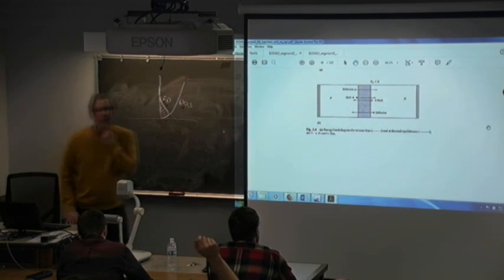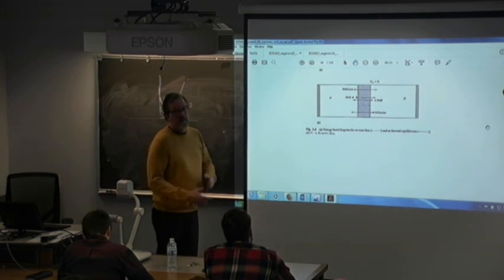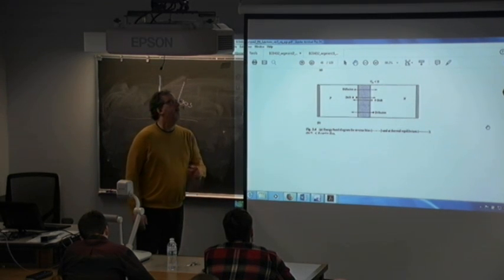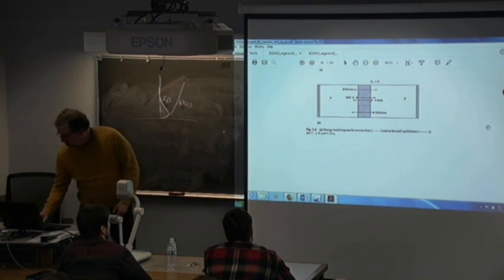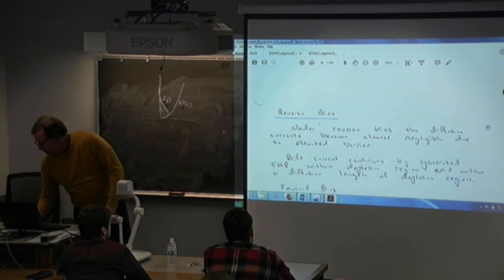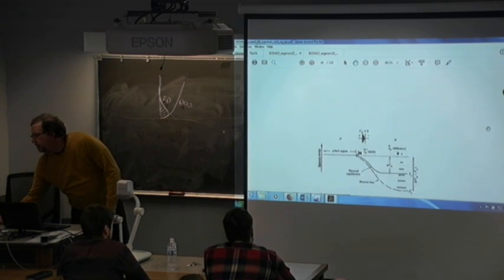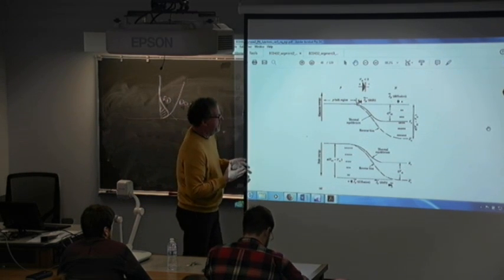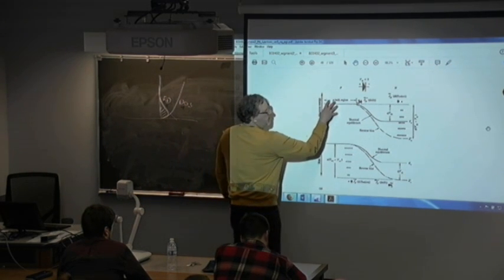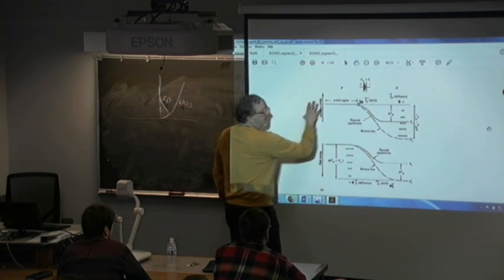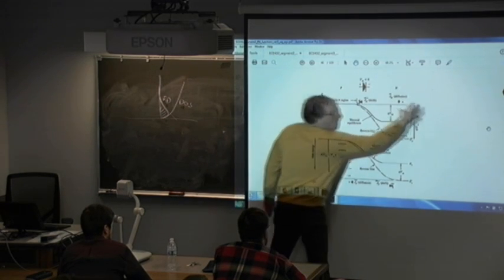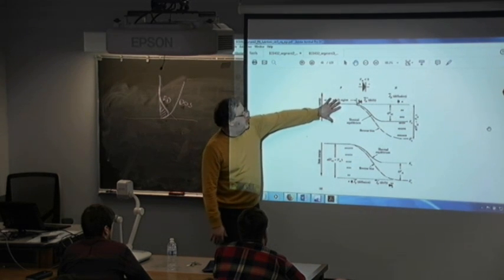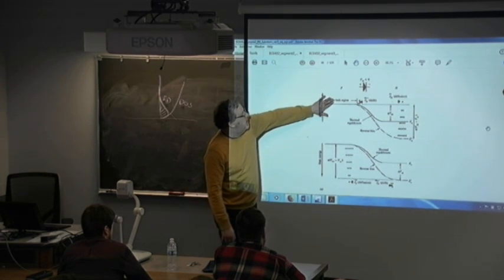Does the reverse bias affect the amount of generation that happens, or just the speed at which it diffuses? Yeah, it's the speed, because generation is a thermally driven process. So recognize that generation is happening way over here on the left, in the middle, and on the right. I just want to emphasize the generation that's happening here in the P bulk.